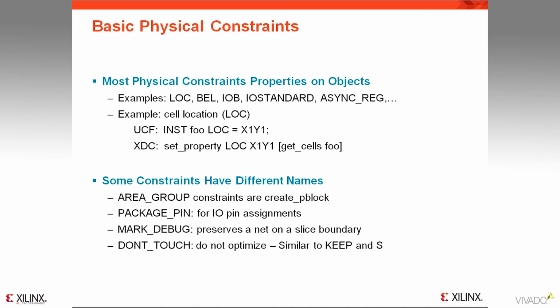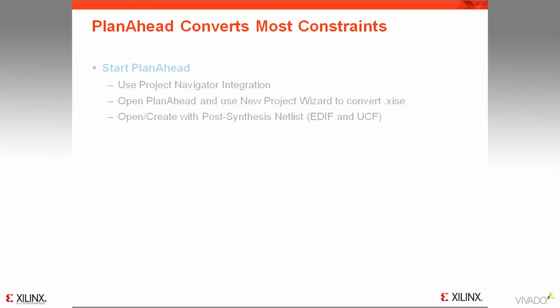In order to use the conversion utility, you need to invoke PlanAhead on your project. You can do this in several ways. Launch PlanAhead from the integration with Project Navigator via the process tree. You can also open PlanAhead and use the new project wizard to import and convert an ISE project file. Finally, you can create a new project with EDIF and UCF, but you need a project with a post-synthesis netlist and a matching UCF to perform this conversion.